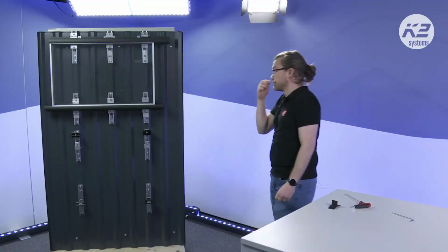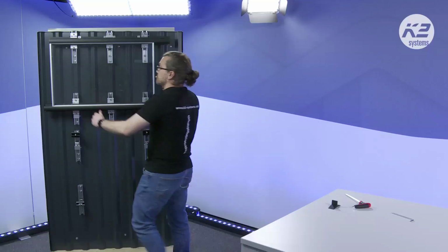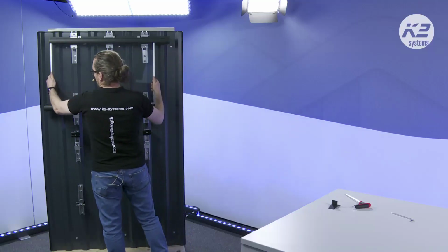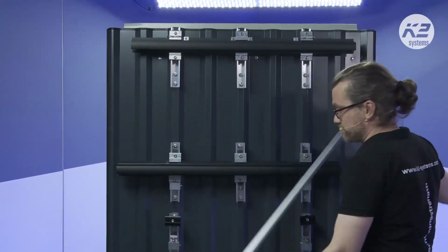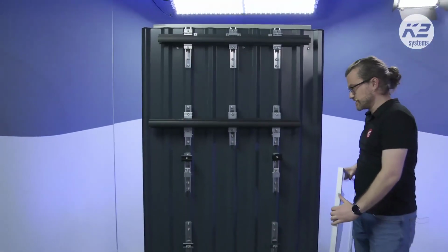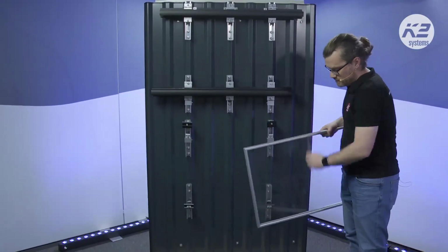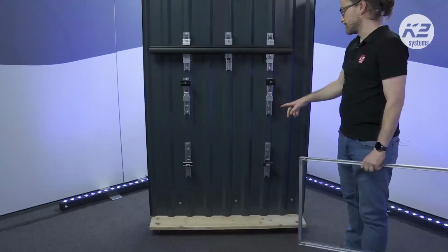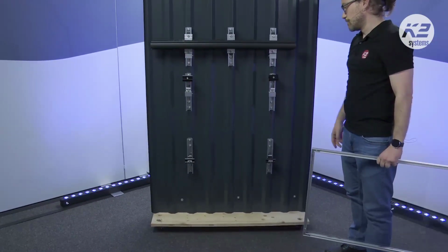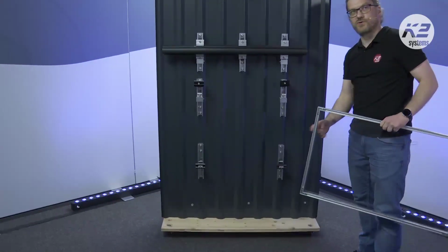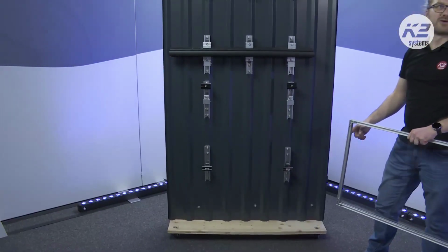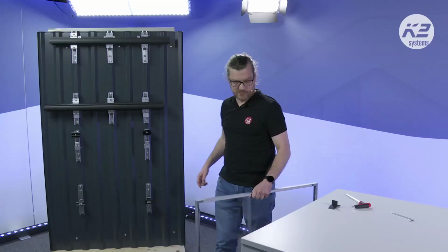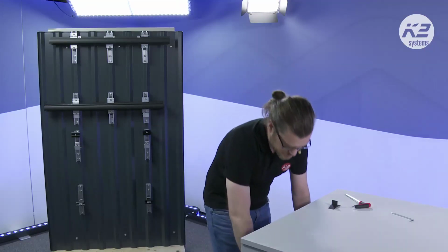So in the insertion rail, you can install modules both, as I said, landscape and portrait. For multi-rail with clamps, it's possible only in landscape installation because you will have to clamp your modules on the long side, and depending on the distance between the crests, it's not always possible to meet the clamping on the short side. This is the reason we use facade clamps only for landscape installation.